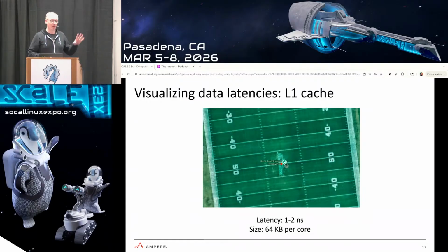But remember, you only get 16K of instruction cache and 64K of data cache. So iCache is where your program lives. Data cache is where data structures that are accessed can live. So you've got small amounts of that data. What that means is that if the data you care about on the fast path of your application is less than 64K, access to that data is super fast, but you don't have a lot of it. Okay?